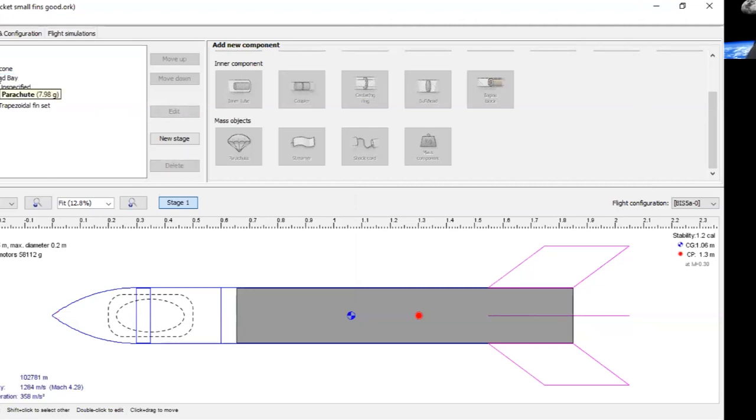Okay, I think that's just about it. I think the basic thing is, don't forget, you can do your basic calculations and see how fast you need to be going to get the altitude you need. But if you're on a planet with an atmosphere, that won't work. It depends heavily on the thrust profile you're using. If you have a very short burn, very high thrust, you'll be nothing like as efficient as if you're burning your propellant and providing your high velocities at high altitude.